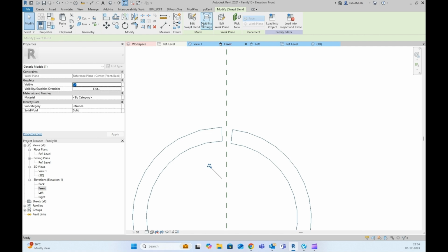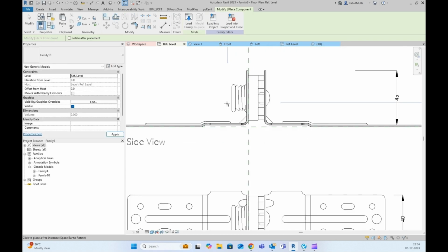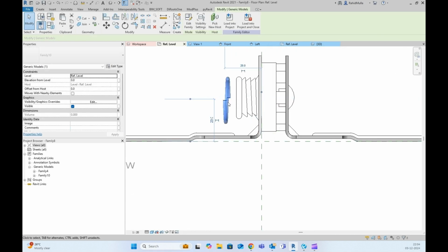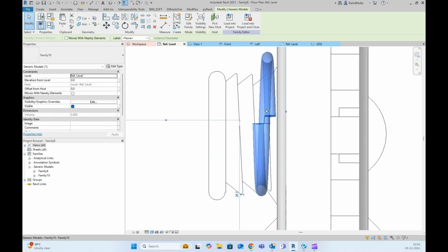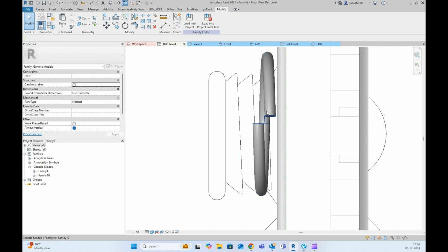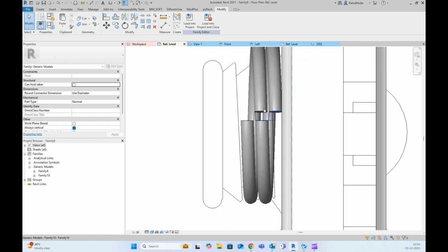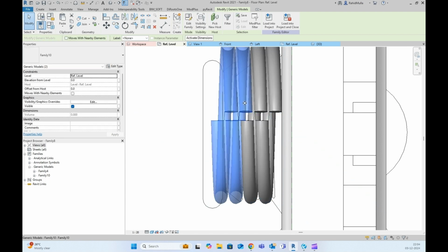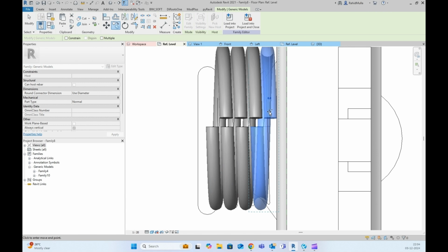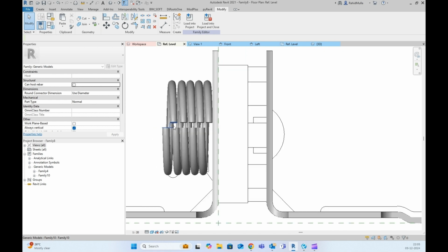I'll close this off, and then I will load this in family 8 or 5. So here once I come, my family is here. See guys, the reason I didn't make this parametric is because we will not be controlling this in the project. We will only make those elements parametric which we will be controlling in the project. Yes, can you see this continuity here? It looks continuous now. Just to maintain this continuity, I have created it in such a manner. So we'll go on copying this until we reach here, and whatever gap is left here, we will fill it with the sweep command.